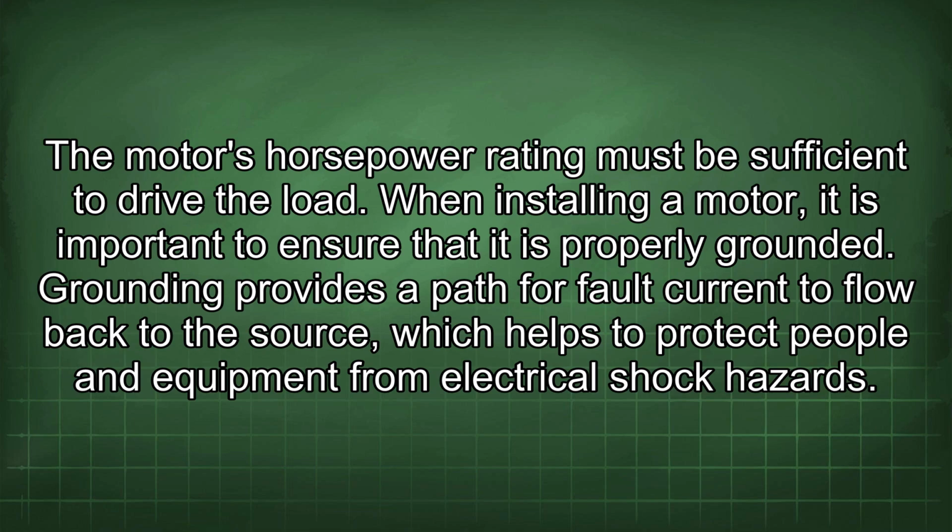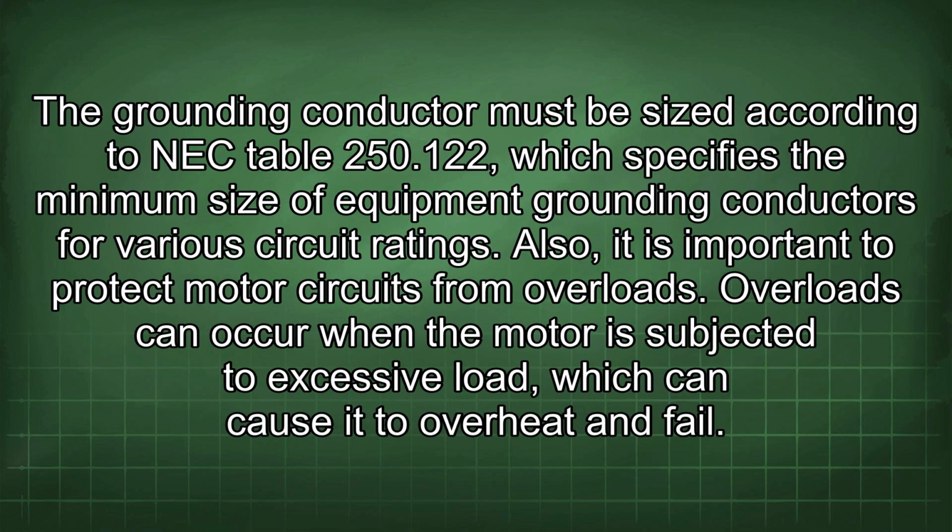Grounding provides a path for fault current to flow back to the source, which helps to protect people and equipment from electrical shock hazards. The grounding conductor must be sized according to NEC Table 250.122, which specifies the minimum size of equipment grounding conductors for various circuit ratings.